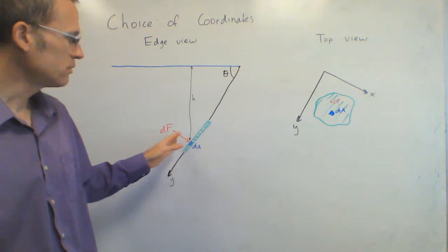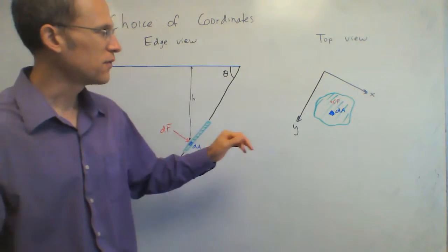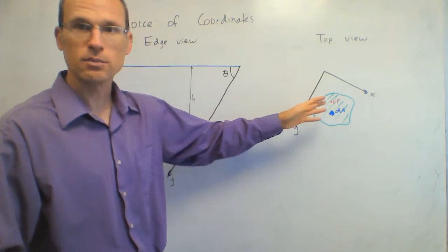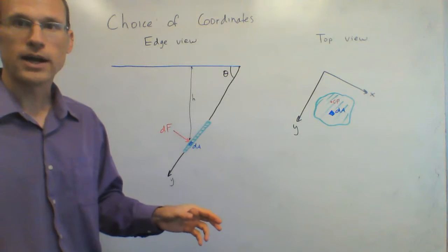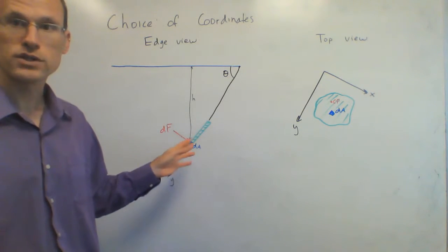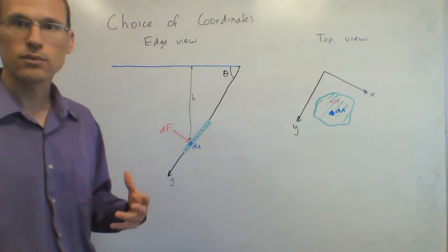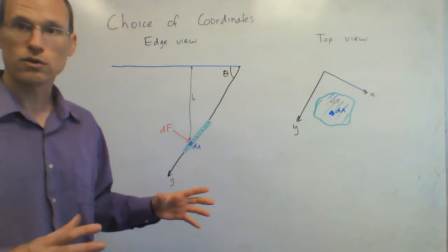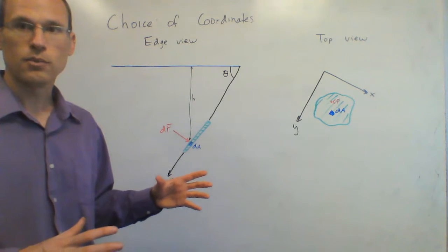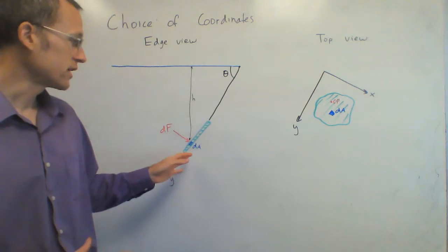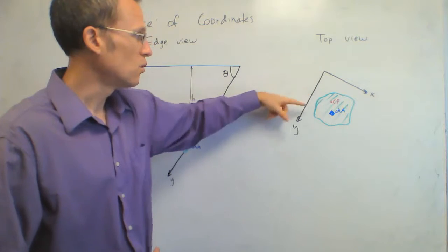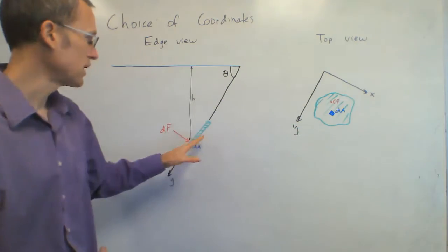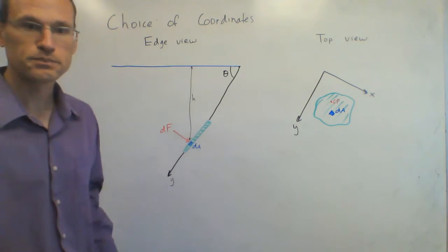In addition to what that actual force is, I want to find the center of pressure, Cp, because the center of pressure is basically where my single point force is going to go. So kind of like in the previous one, if I had the horizontal plate, the point load goes right in the middle. This is not necessarily going to go right in the middle. It's going to go at some value Cp, which has some y coordinate and some x coordinate based on where this plate is.